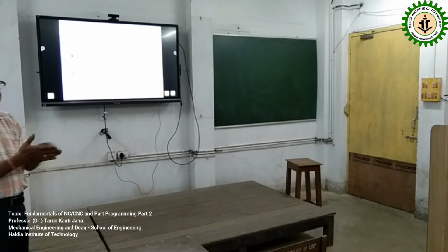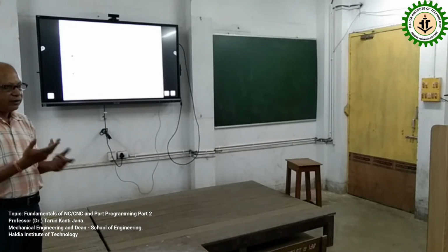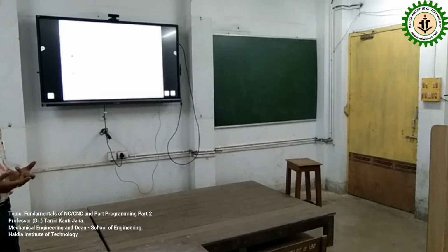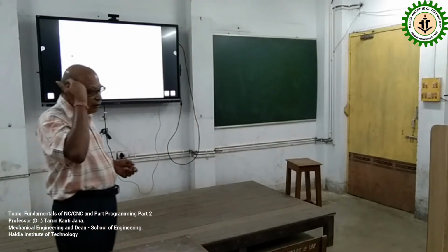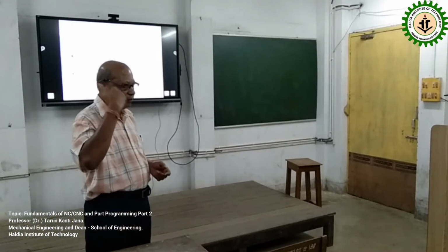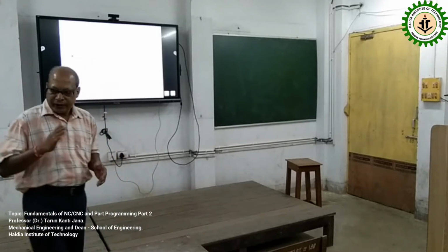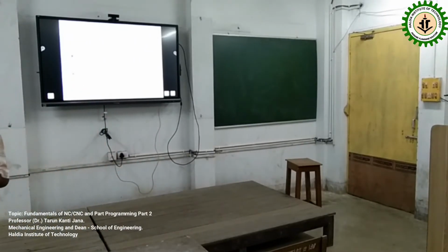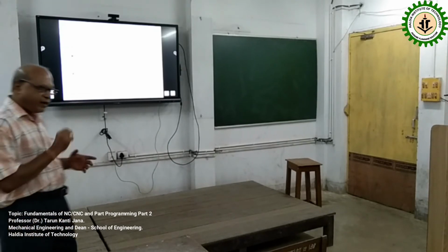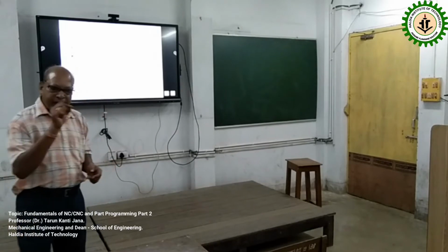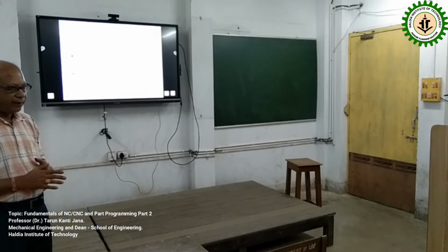Will you be able to measure the level of wear of your blade? So what is the experience? You experience that you need more force to cut. When you feel through your experience that the force is increasing abnormally, then you replace it. So here also it is very difficult to measure the magnitude of wear, and to know when to replace the old one.